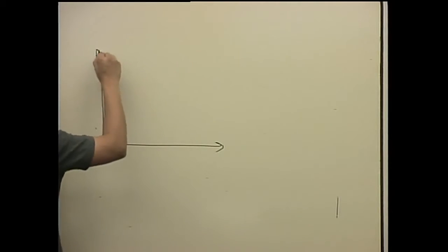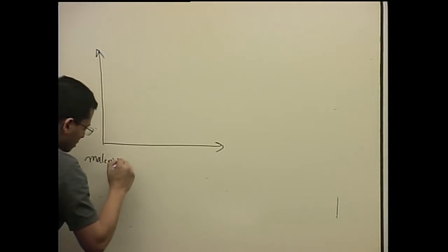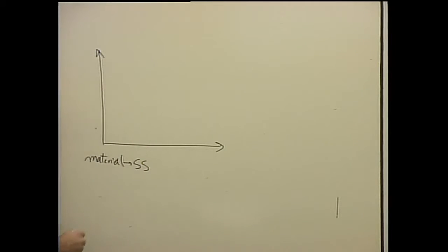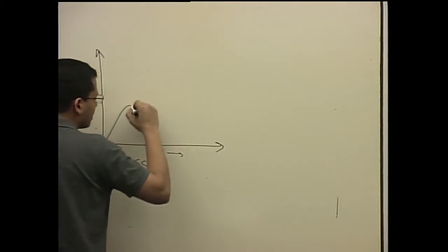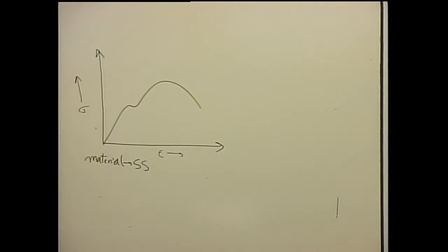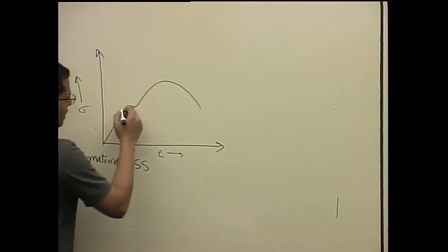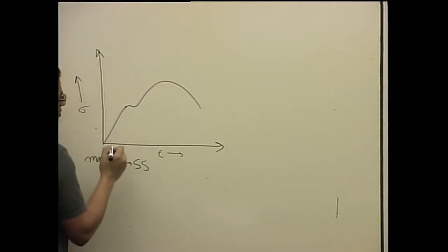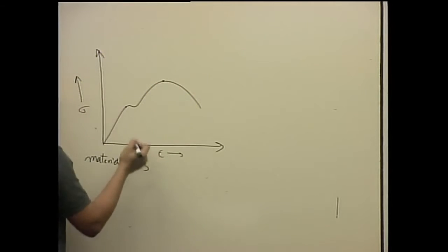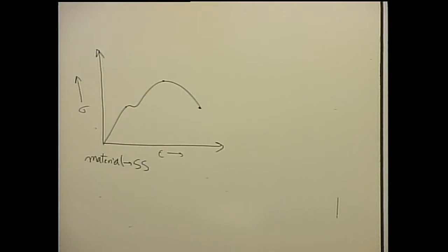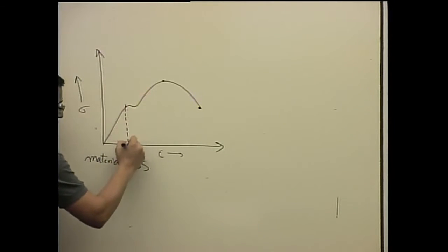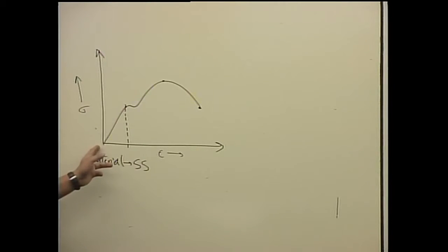Let's say we have a material which is stainless steel. Just some recalling: we have the strain here, the stress here, and the stress strain curve looks something like this, right? Familiar with this stress strain curve for steel. Then we define this point as our yield point, this point as the maximum stress or strength, and then ultimate tensile strength. So this is our elastic range, where the system starts to go plastic.